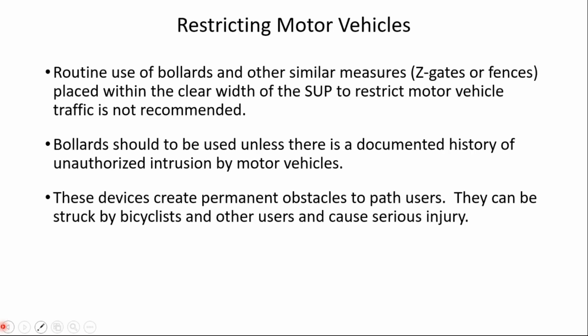So how do we restrict motor vehicles? That's one of the challenges. Many agencies use bollards of various types or similar measures like Z-gates or fences that are placed within the clear width of the shared use path to restrict motor vehicle traffic.